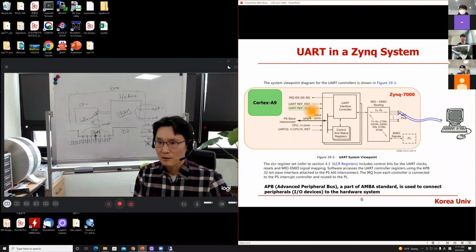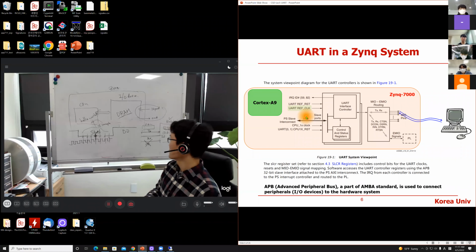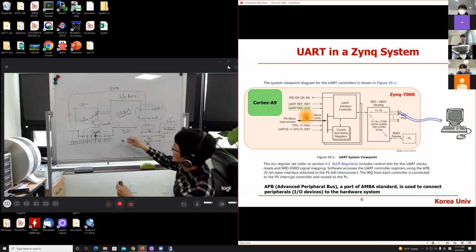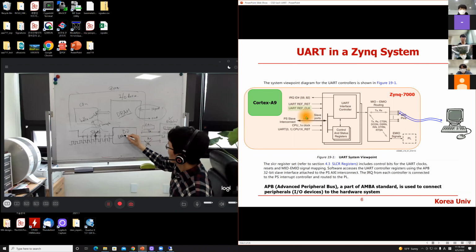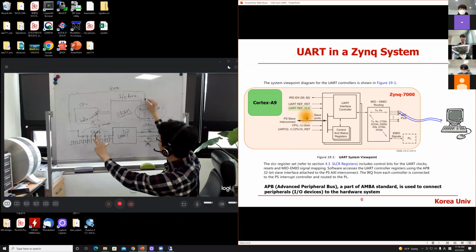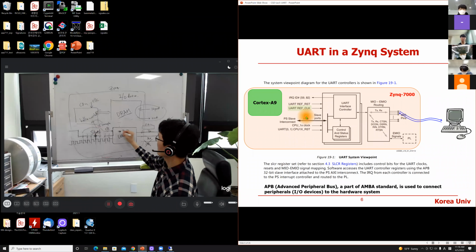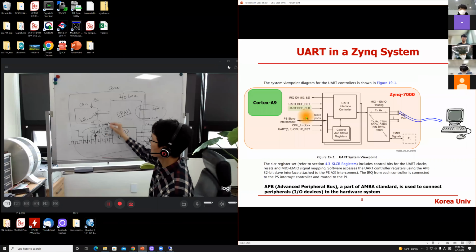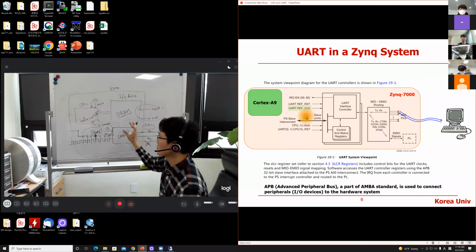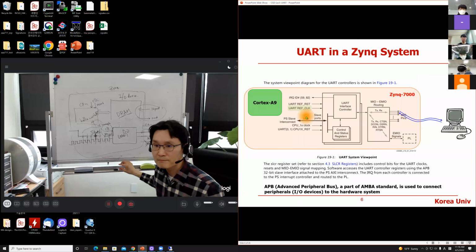It is also receiving a clock. Every I/O device, not only the CPU, every digital device should have a clock. Even though between the notebook computer and the UART there is no clock signal involved, internally you should have a clock. The CPU is taking a clock, and the UART should use a clock and reset. Those two are default input signals for every I/O device: clock and reset.